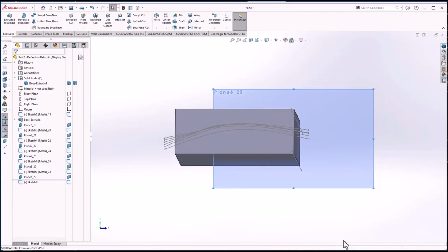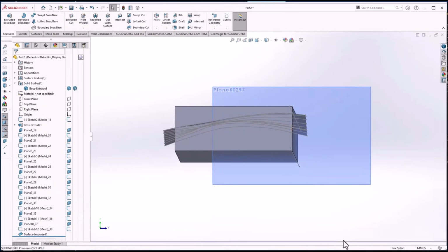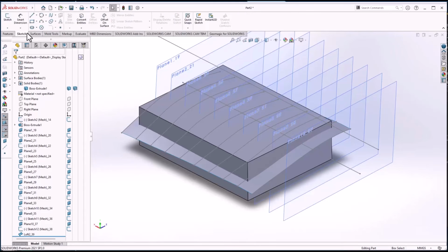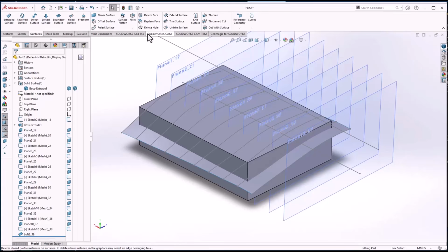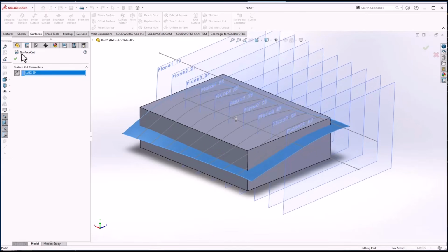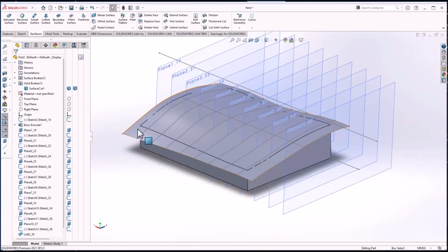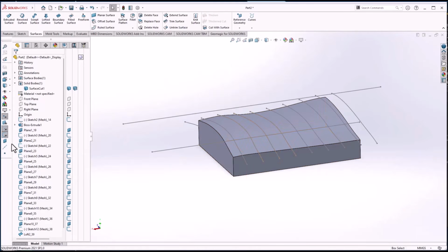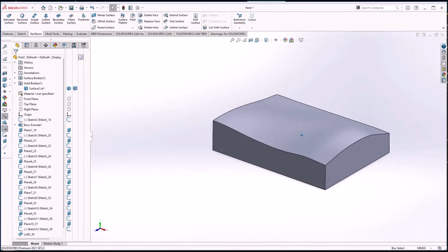And you'll see that it's building those 2D sketches in, and it creates a loft for me, and it says export succeeded. And then you just use your regular surface modeling stuff over here, where I say I want to cut with surface and flippy flip. Hide it. And there we go. Hide all my planes. Hide all my sketches. So there we are so far.